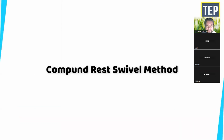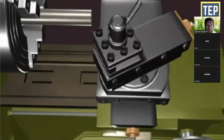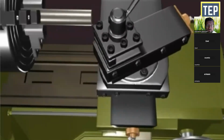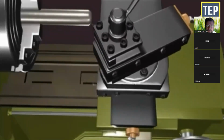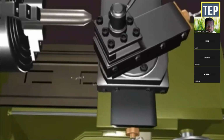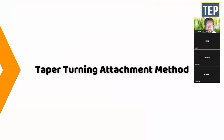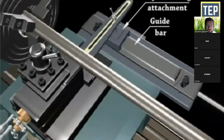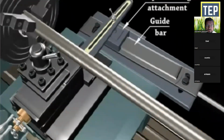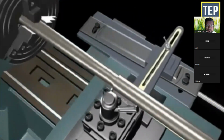Compound rest swivel method. Here the workpiece rotates and the cutting tool is fed at an angle by the swiveled compound rest. The base of the compound rest is graduated in degrees. Once the compound rest is set to a particular angle, the tool is moved by the compound rest and wheel. Taper turning attachment method. This method is similar to the compound rest method. Here the job or workpiece rotates and the tool is fed at the taper angle.